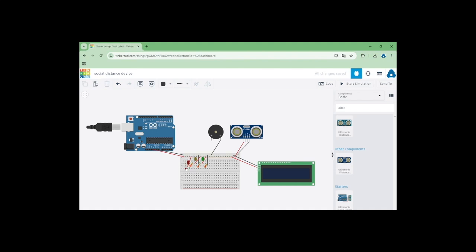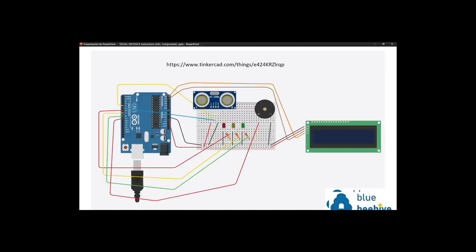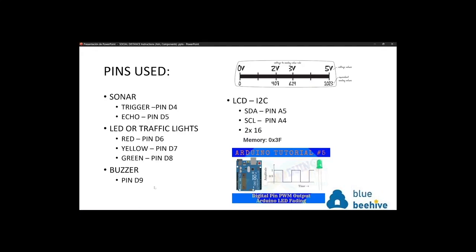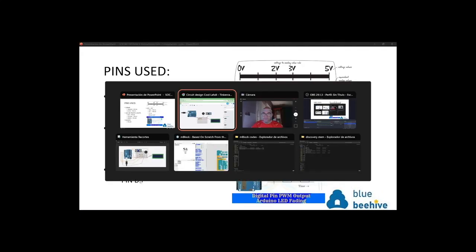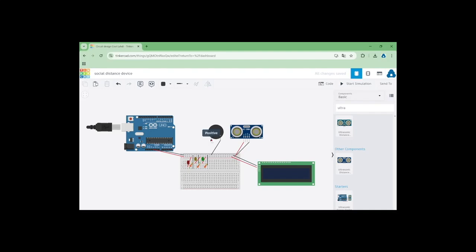We go to the positive, we put it directly on the anode, cathode off all the LEDs. Also goes to the poles and also here. As you remember, in the buzzer, we just need to connect the buzzer to the correct port we have here. Remember, the buzzer will be digital pin 9. Digital pin 9 means buzzer. I will use, for example, the green to be sure that it will go to digital 9. Okay, the buzzer is now connected to digital 9.